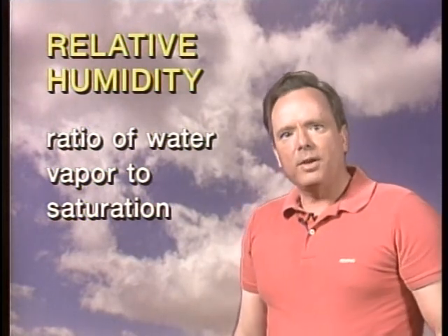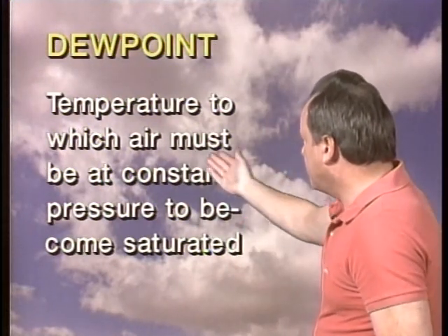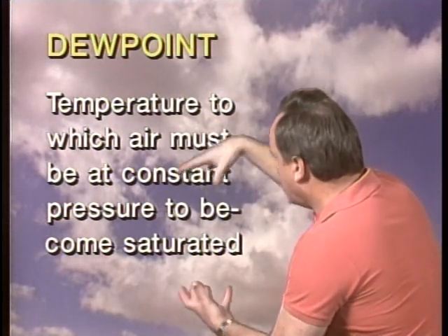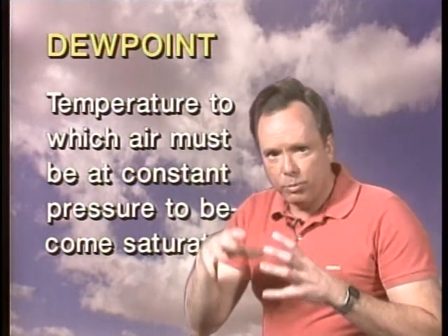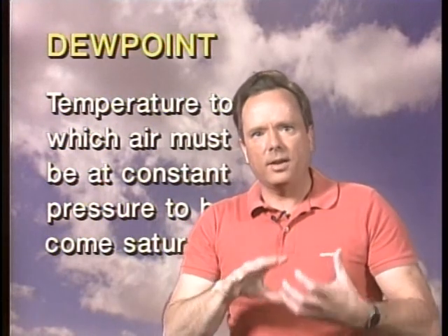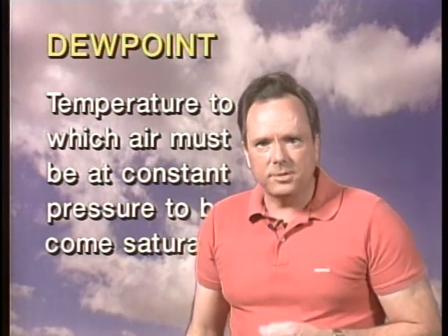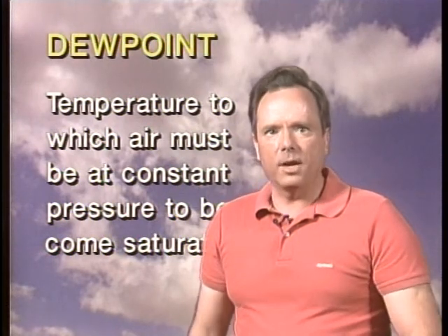They're also going to ask you about dew point. What is dew point? Well, dew point is the temperature to which the air must be lowered at a constant pressure. You lower the temperature of the air to become saturated. So it's the temperature to which the air must be reduced to have saturated air. And so on the test, it's going to go like this. Dew point is the temperature to which humid air must be cooled at constant pressure to become saturated.